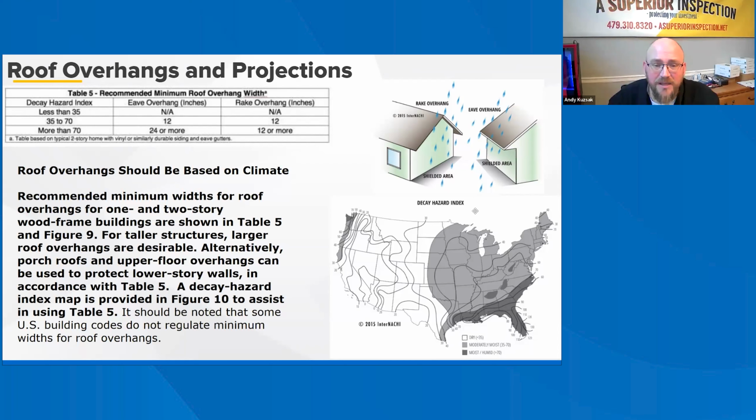So when you don't have those, I would pay special attention to the framing around the doors and the windows. Not so much windows, because they should all have the interior J channel and the flashing and all that kind of stuff. But in my area with my inspections, it's more often that we find damage around doors that do not have an overhang. So keep that in mind.